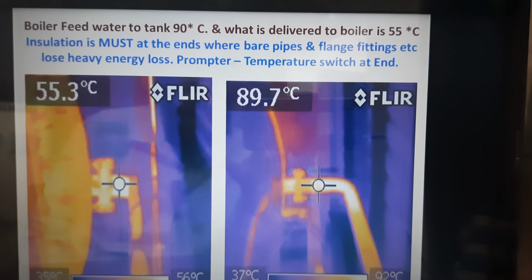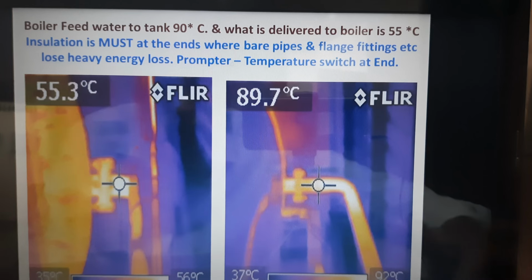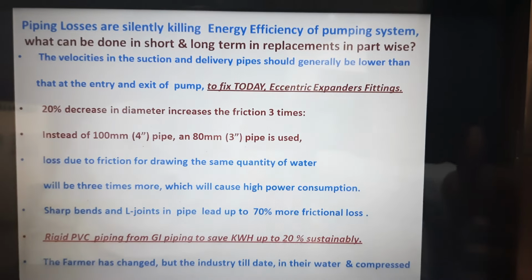Wherever you are using a steam system, you need to have insulation end to end on all the piping, and not only on the piping, it needs to be on the flanges and the fittings as well. If it is not possible to do aluminum-cladded glass wool insulation, you can even use an asbestos roof sheet on your steam piping and fittings. Definitely, the heat is then kept within the piping and does not escape to the atmosphere. It is a huge loss that is silently happening in your industry.